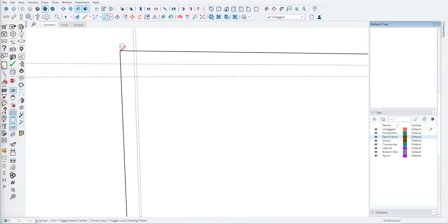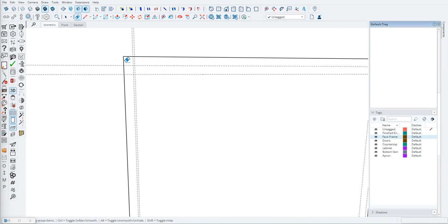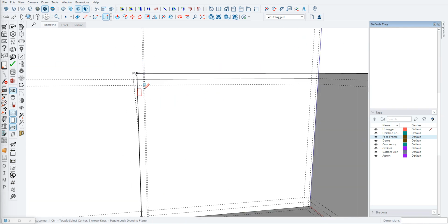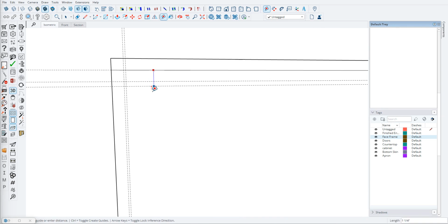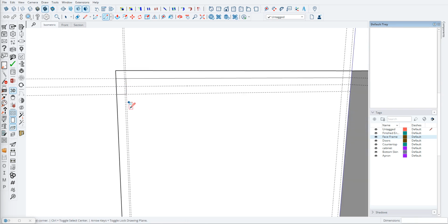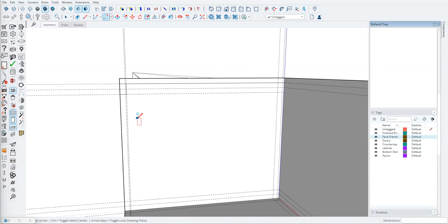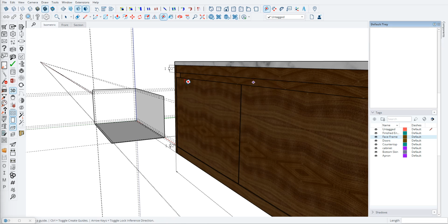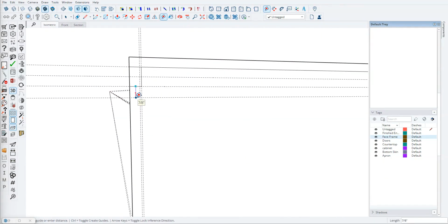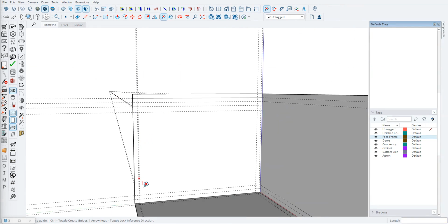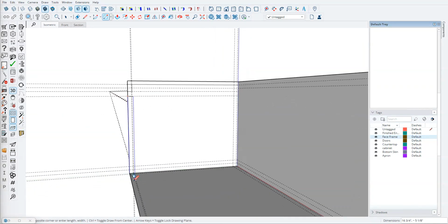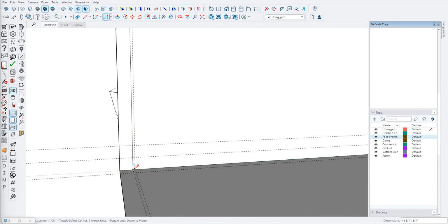So here is, so you can start drawing these in as to not get confused with all the different guidelines. So that's the countertop, and then I'm going to come down 1.5 inches, and that's going to be my top rail. Okay, and then if you remember, this is a 1 inch space here. So from there we're going to make another guide 1 inch down, and then we're going to draw a rectangle down here, and then this is the door.